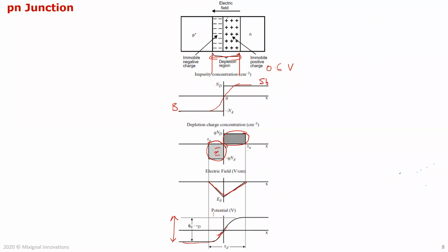So the question is, why is it more here than here? As you can see, I've written P plus here. Now the question is, why did it do a P plus? That again is a little involved because you can't just do N plus. If you do, your diode characteristics won't be a good diode. Basically, it won't be exponential in nature. That's when you derive the equation, and you'll figure it out.